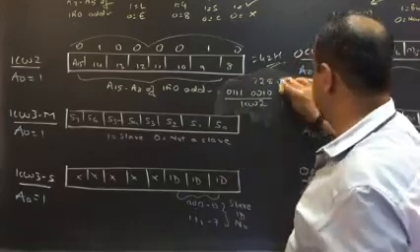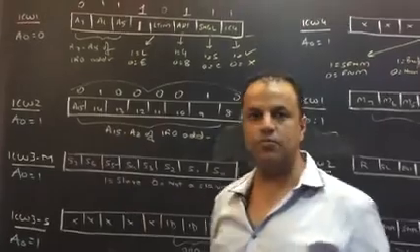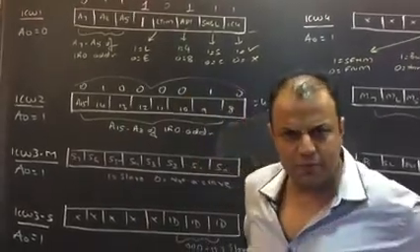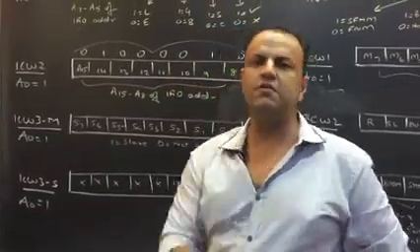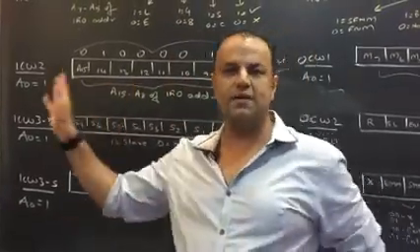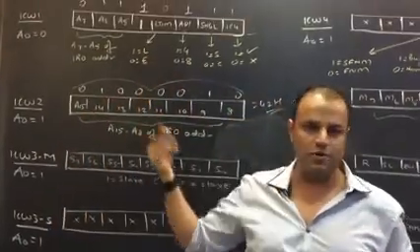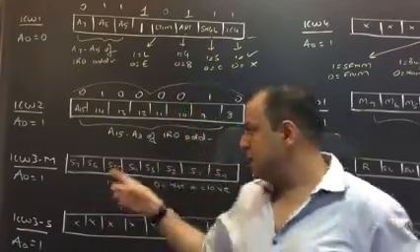Now that you understood this, you have understood what is ICW1 and ICW2. With this, your compulsory commands are over. Like I said, if it's a simple exam that you're preparing for, like your college exams, many a times the programming question doesn't even involve any other command. This itself is enough to write a programming answer. Whatever parameters they specify in the question, based on that you write the bits and you give the commands and you're done.